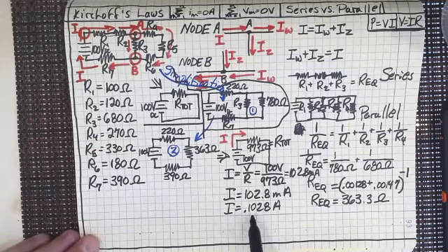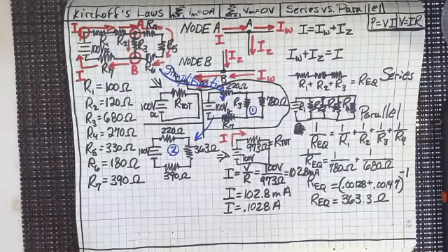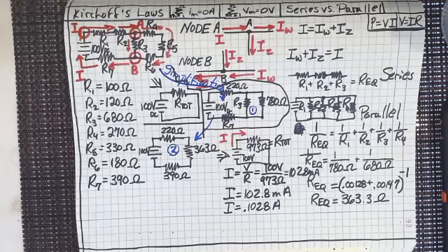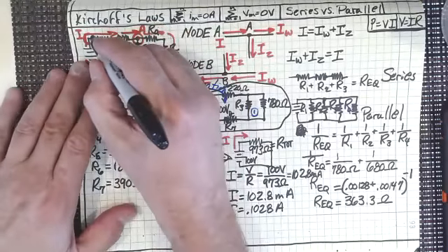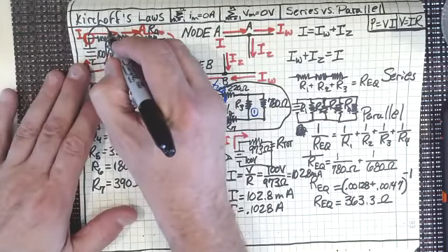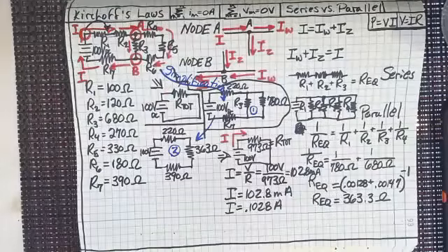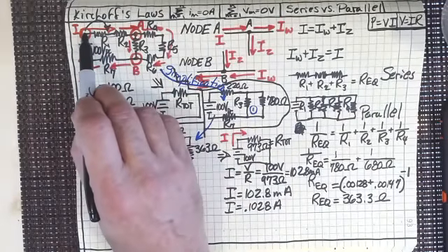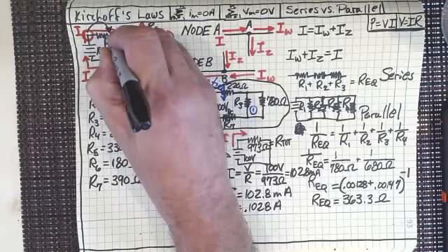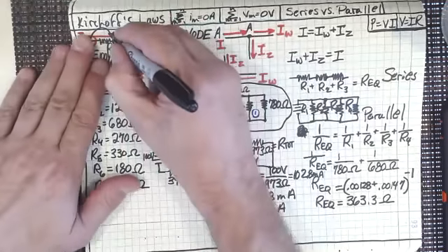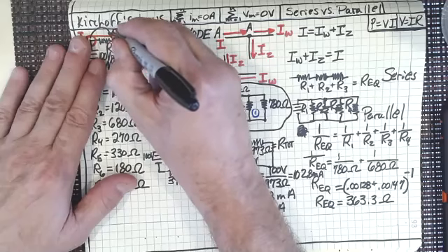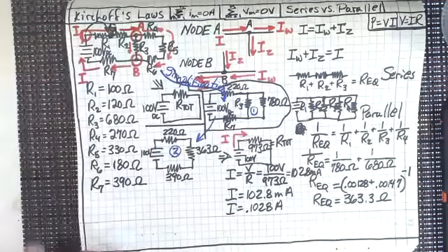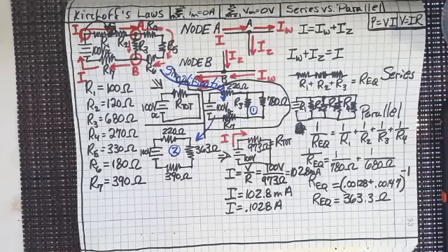So what we're doing now, we know that the current is 102.8 milliamps coming out of that. So what are the resistors that we're going to see first? Well, aren't we going to see the resistor R1 first? What's that voltage drop across R1? We know the current's flowing from the 100 volts to whatever this voltage is right there. I'm going to call that spot G. That's right, for Professor Graham. That's spot G.